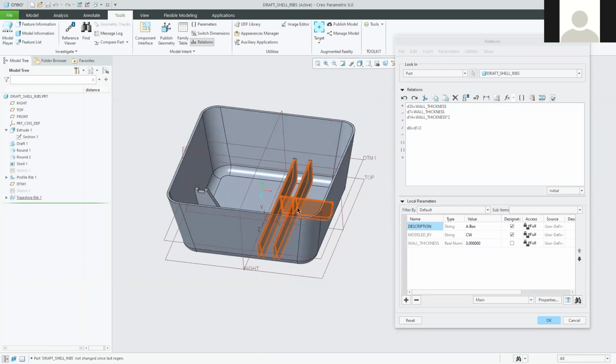So what I want first is the value that's defining the height of this second rib, and that value is governed by the position of that datum plane that we created. So that datum plane is a set distance away from that top plane. That's how we defined its position. So it's actually the height of that datum plane that we want to calculate. And we want to calculate it as 60% the height of that rib. So let's see if we can do that.